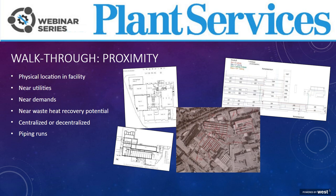Plant piping runs should also be considered when placing your compressors in the plant, as well as centralized or decentralized compressor rooms. Pipe size, length, and type, such as branch or loop, will also affect overall capital cost, but it will in the end affect production via operating costs and possibly air quality, which we'll talk a little bit about later.